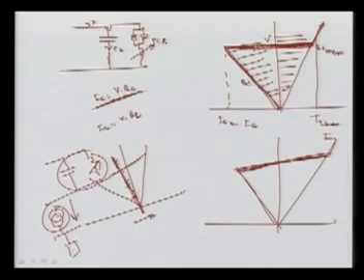Regulation, that is a droop or slope, tends to enforce automatic load sharing between the static compensators and other voltage regulation. Due to the coupling reactance, the voltage drop is normally 10 to 20%, but the slope reactance is typically between 2 to 5%. So we don't want much slope. This slope is still not desirable. So we try to go for the minimum slope that is required, so that we should not have hunting, and at the same time we can have stable operation.